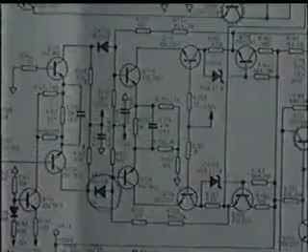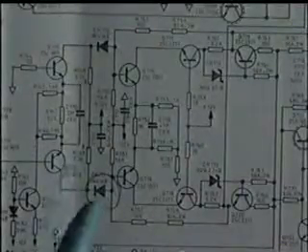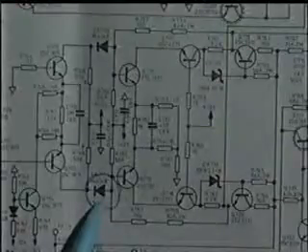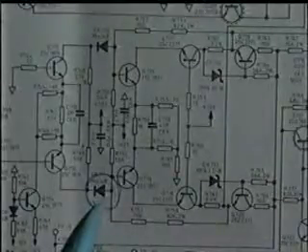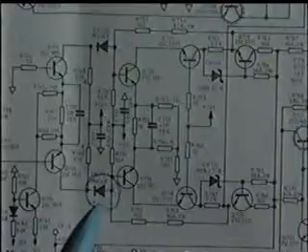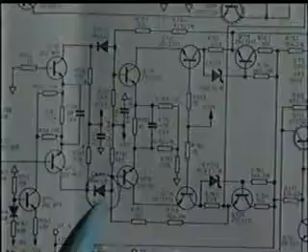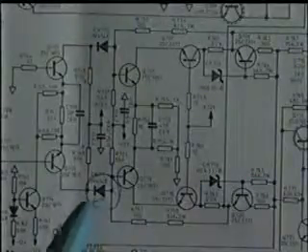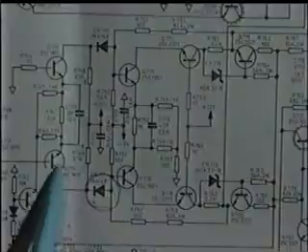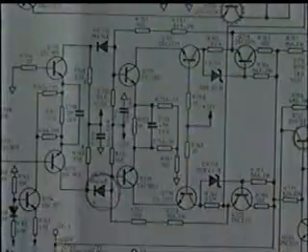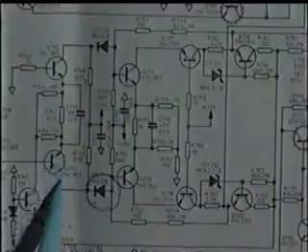Suppose in case any transistor had gone out of order, then how would we have checked it? Let us see the circuit once again. We have seen this diode was defective and we have replaced it and the problem is solved. Now look at the circuit properly and see if any of the transistors had gone out of order. All these transistors are DC coupled.